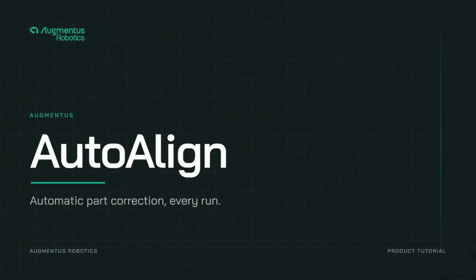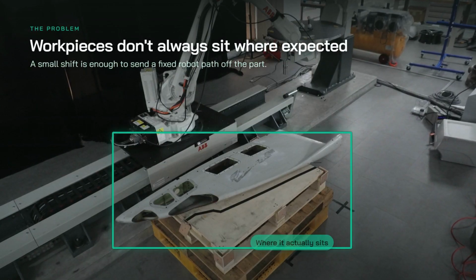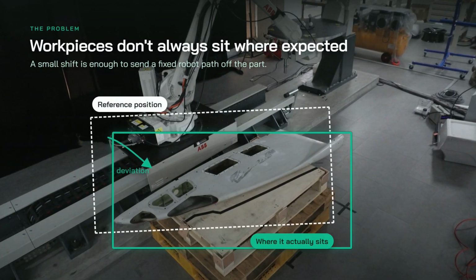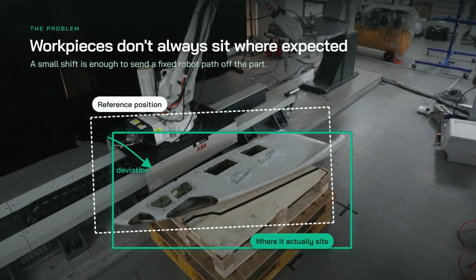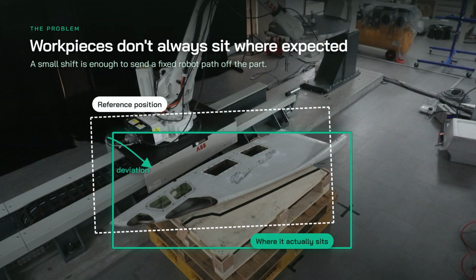This is AutoAlign, the automatic part correction system in Augmentus. In this walkthrough, we'll set it up end to end, from a reference scan to a corrected robot path. In production, a workpiece rarely sits in exactly the same place twice. Even a small shift from its reference position is enough to send a fixed robot path off the part. AutoAlign corrects for that deviation automatically on every run.